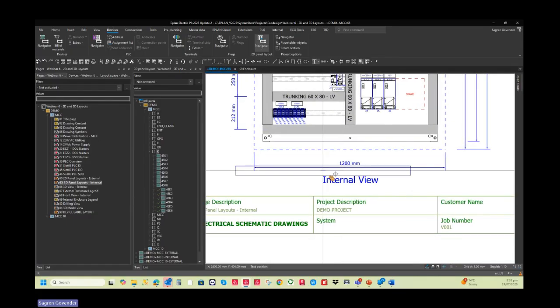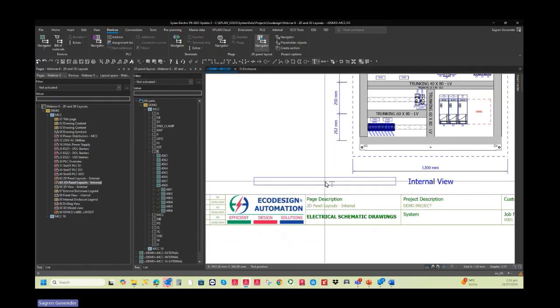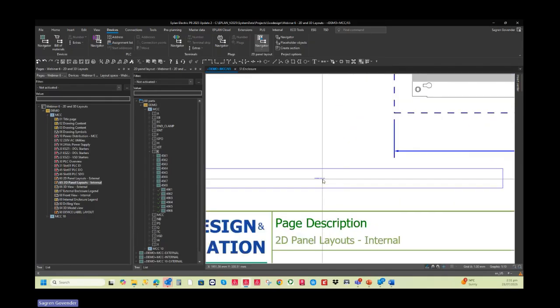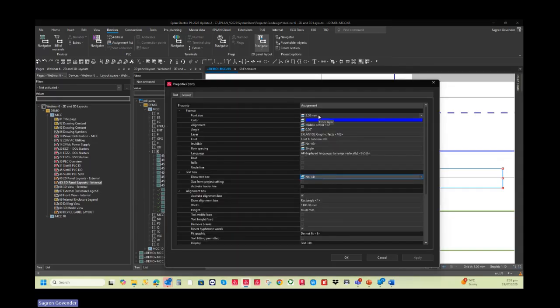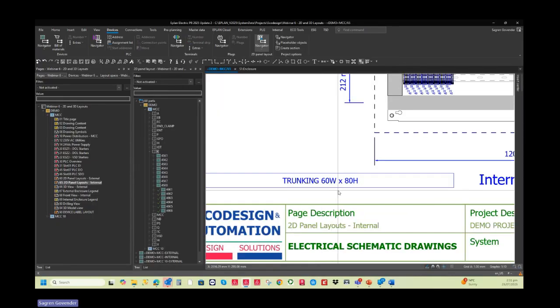it's going to place. Oh, actually, one thing I forgot to do was I'll place it here in any case. I forgot to change the font. Because my panel is scaled 1:10, I need to scale this as well. So I'll just make this 25. And now that's a reasonable font.